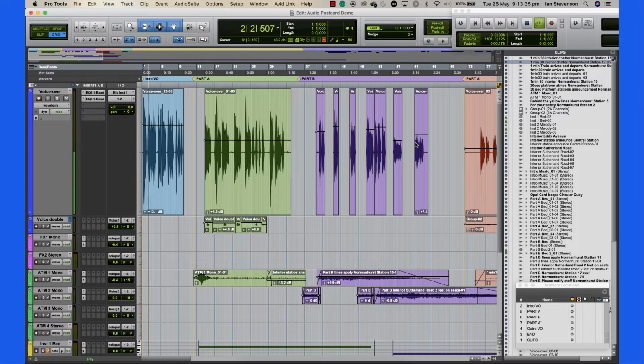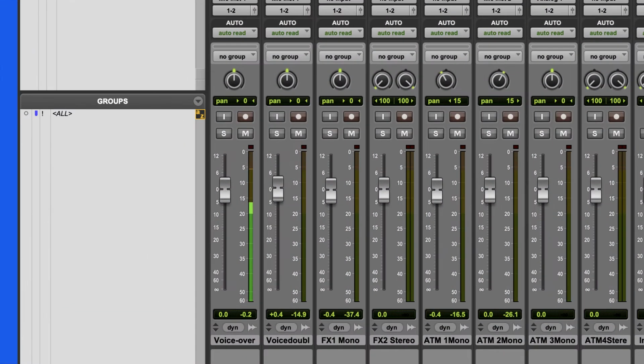Understanding gain structure. The signal level meters enable you to measure the average and peak levels of the signal you are recording. Signal levels are measured in decibels or dB. The maximum level that can be recorded in a digital system is shown as 0 dB. All levels below this are negative decibels. The solid part of the meter smooths out the rapid fluctuations in signal level to show the average. The instantaneous peaks are shown with the green line that floats above the average level.